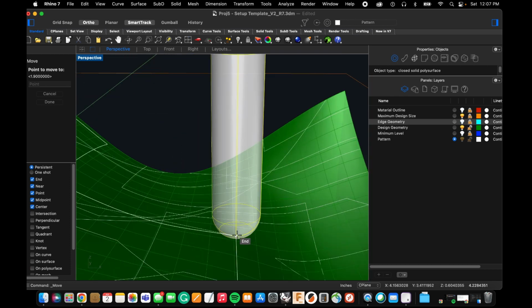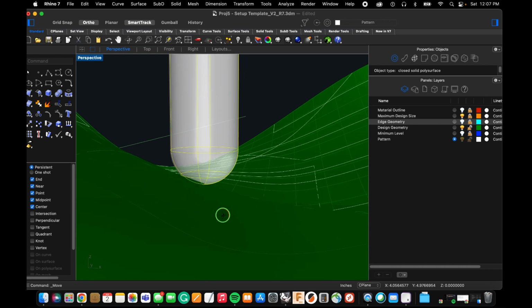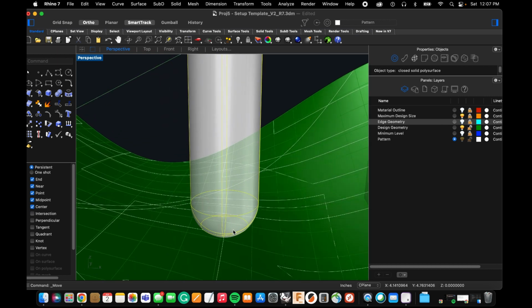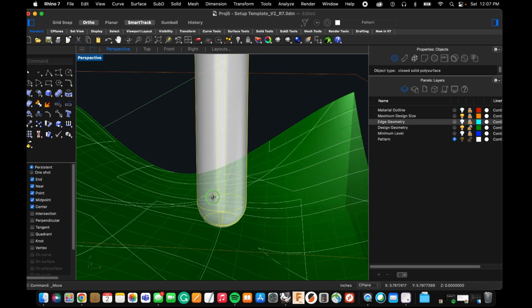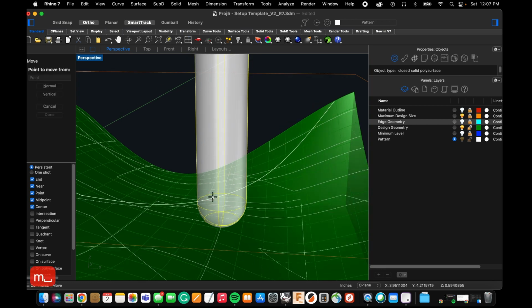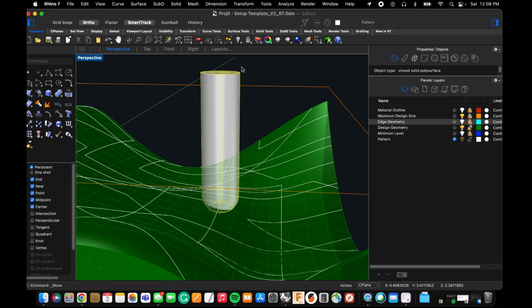Okay, so if we take this and we go to the midpoint and we just bring it down onto the surface. Okay, the tool is going to follow this curvature as it's projected onto the surface. Now we are specifically programming it so that it's actually going to be cutting into the surface, and with a 1/2 inch, that's going to be negative 0.125.